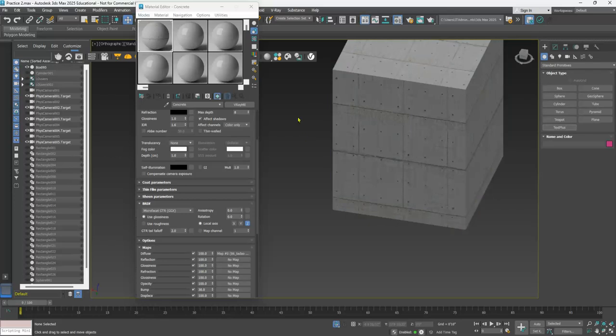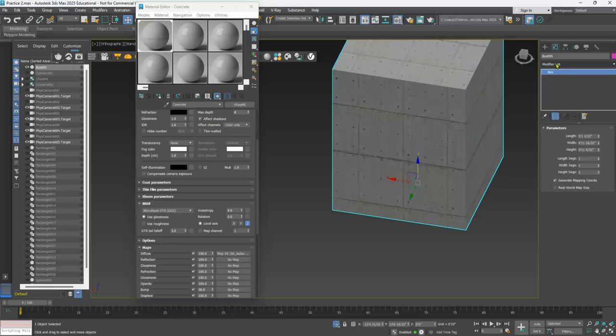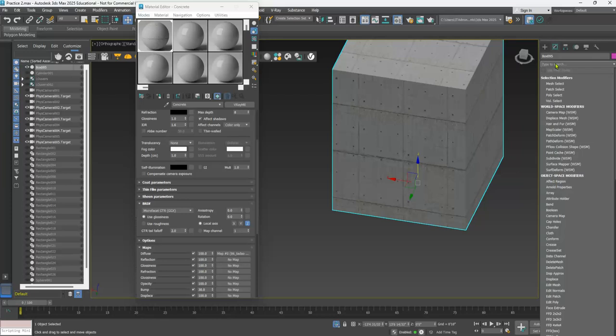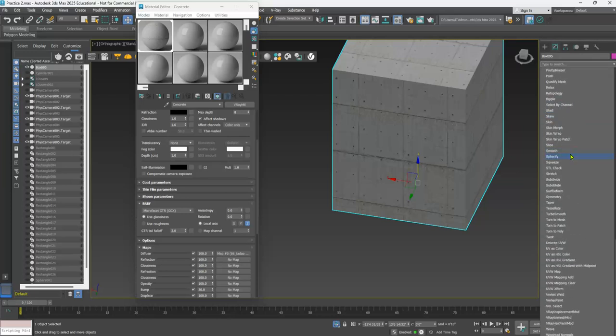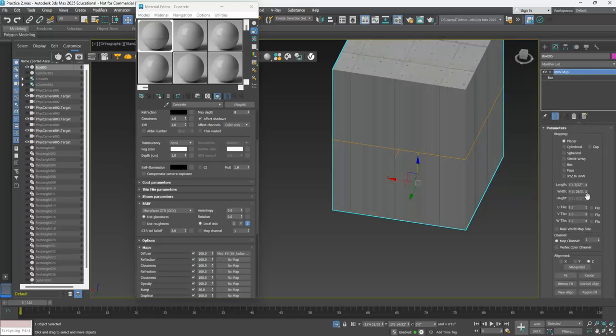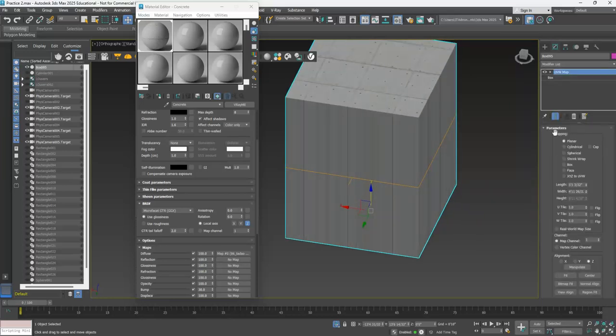Yes. So I'm gonna pick the box, right? Select it, go to the properties, and we're actually gonna apply two systems. One that tells 3D Max what the object looks like, and the second one is how to scale it, make it bigger or smaller. So the first one is I'll go down here to the one called UVW map. And this tells 3D Max, so it gives you a very simple list here: planar, cylindrical, spherical, box, shrink wrap, and face. From these shapes, what is the closest thing that this box looks like?